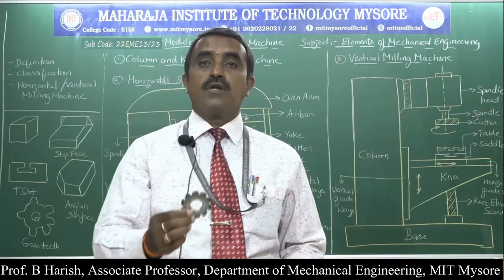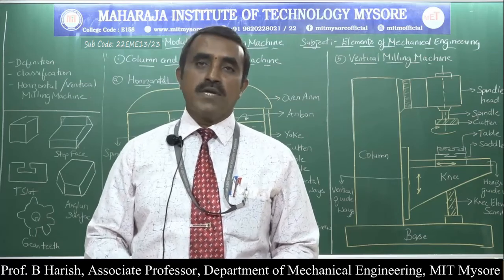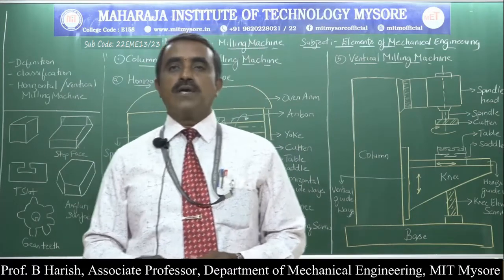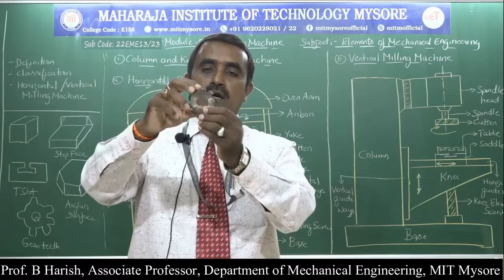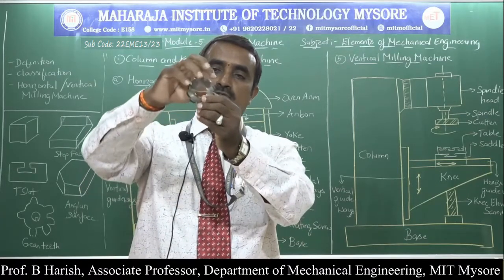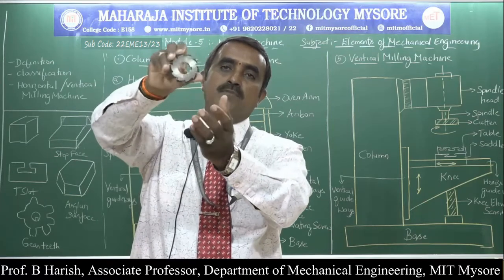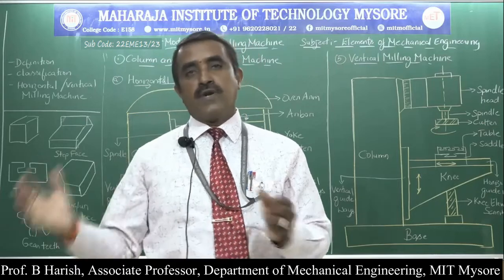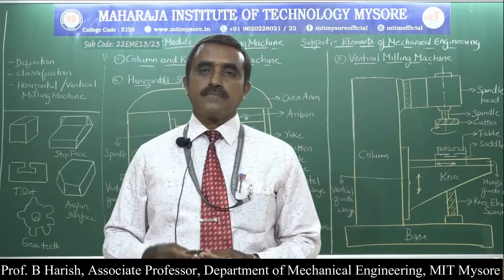This type of cutting tool is used in the milling machine, and similarly in the drilling machine we also use a multi-point cutting tool. Whereas the lathe uses a single point cutting tool with only one cutting edge. Here, every tip of the teeth on the cutter removes the excess material as it rotates. That is how we can differentiate the milling machine from other types of machine tools.